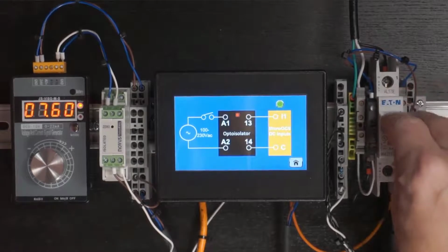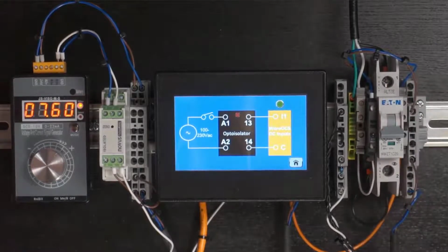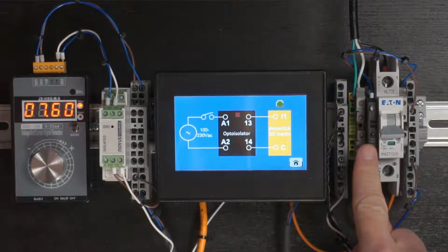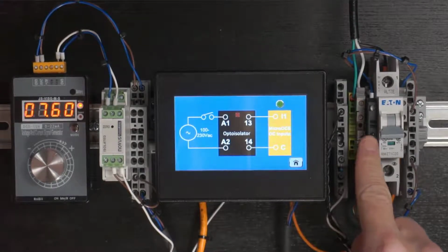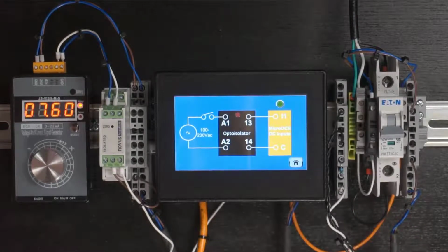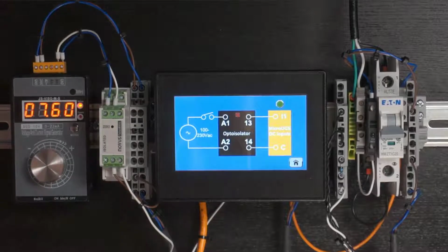Now the beauty of these devices is that you basically use one per AC input that you have. So if you've got, let's say, 3 AC inputs total in your system, you would use 3 of these optoisolators, and they're not all that expensive, frankly, and then the rest of your inputs are still available for standard DC type inputs. So that is the optoisolator for AC type signals. All right, let's move along.